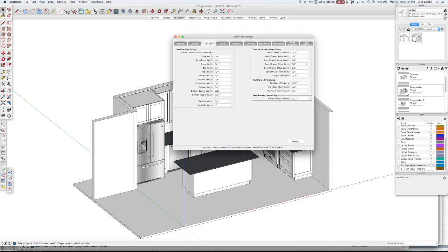For example, when I build doors, I build my stiles and rails oversized in width so that I have the ability to size the doors up later, and also the way we mill our door frame parts is using the shaper and an outboard fence, so I want a little extra width on my parts for the shaper to take off and make a clean cut. So for my door and drawer styles in width, I add an extra 1/8 inch, a 1/16 inch for the shaper, and a 1/16 inch so that I build the door oversized and have some extra material to fit it to an inset opening. I have to make the stiles an 1/8 inch longer accordingly to match the extra width in my stiles.